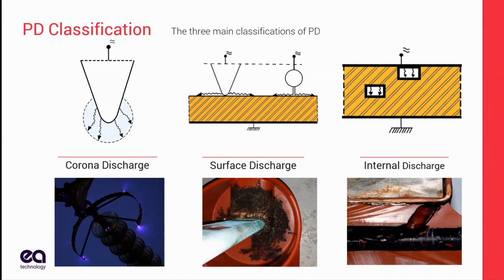The second, and the most common and the fastest moving, fastest growing partial discharge, is surface discharge. This is characterized by the current path being the interface between the insulation and air. As you see here in this picture, and this is 6-year-old switchgear, you get this tracking across the surface. What we saw in the video in the last slide, that surface discharge, the current is trying to find a path to ground. While it's doing that, it's damaging the insulation. It's leaving a carbonized track behind it.